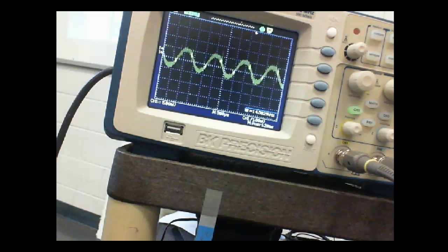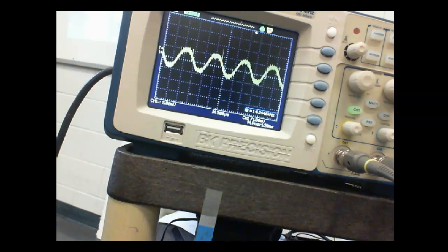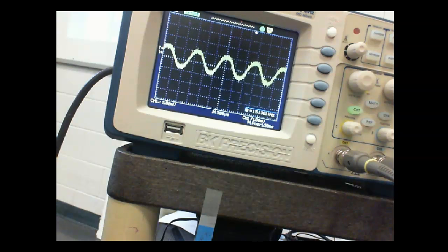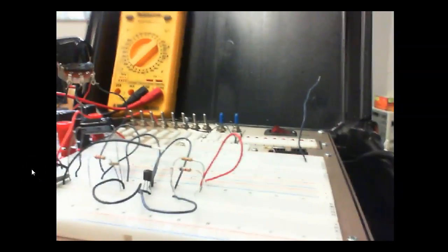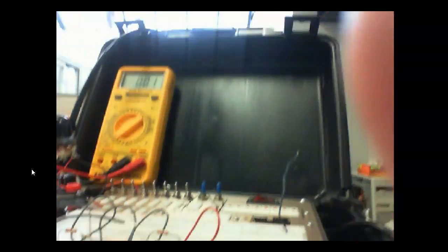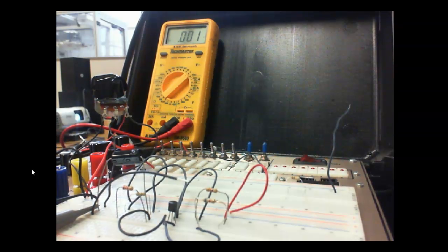And we're going to use the color coded values to calculate our voltage. And then we're going to calculate VB, VE, IE, and the DC levels. So y'all go ahead and do that. And then we're going to come back and measure and see how we did.